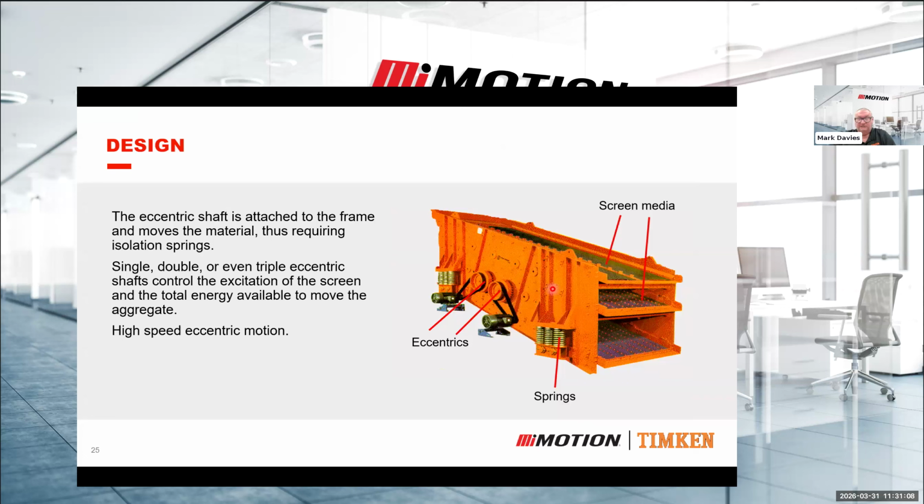You can see on this one here, you get dual shaft. You can get single shaft screens. You can get triple shaft as well from Cedar Rapids. They're the only ones I believe that make a triple shaft. And in this case here, you also get a single, double, and triple deck as well. So it's going to screen out 3 different sizes of product, plus the overflow as well. So it's really a quadruple. So it can be quite high speed in the drives.